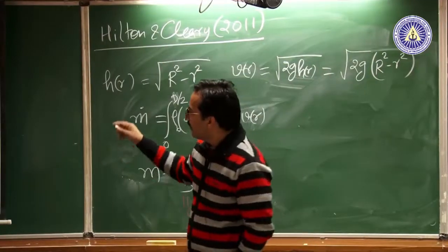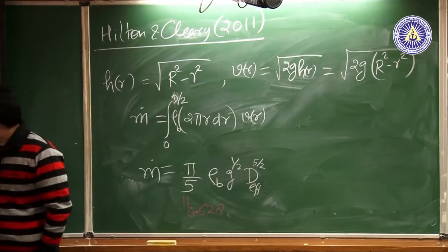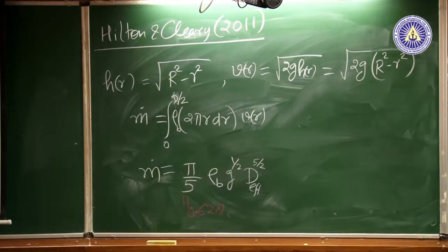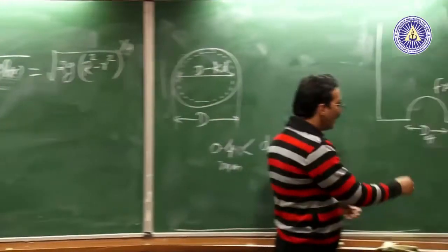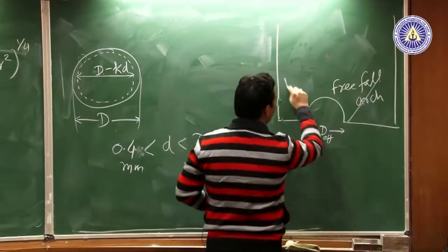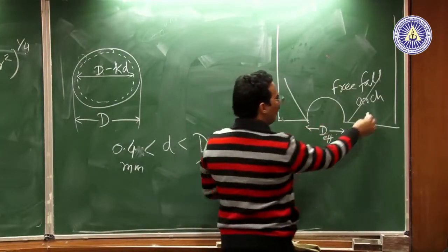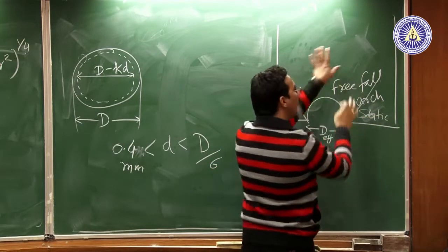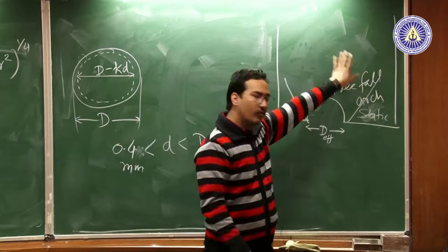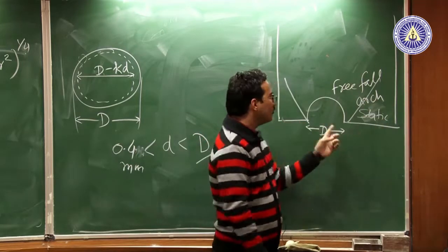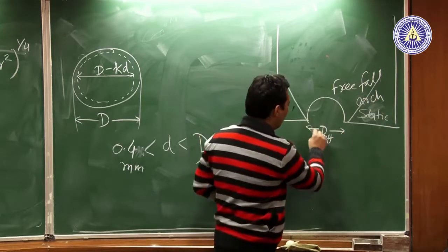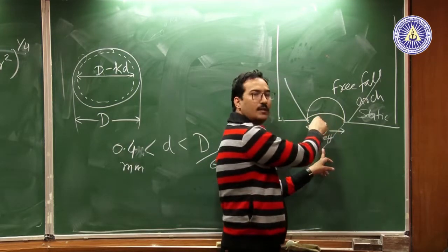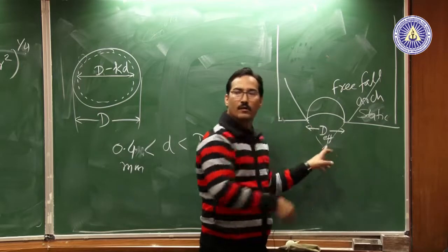And what you also see is, by the way, people have also tried something like a spherical section. Just like somebody asked, why hemi? If you look at this, you will see the flow primarily occurring in a zone, in a region. You'll have not much flow here, a static region, and then a flowing region, somewhat little flow, but it's flowing. There's virtually no flow here. So people said, well, we can think of it like a spherical arc, and the particles are free falling in that region, and you can predict those.